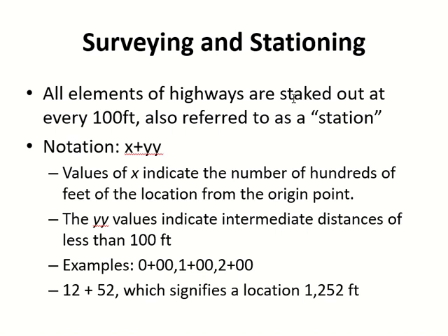Okay. So this means how much? 12 stations and 25 feet. Like total how much distance? 1200 feet plus 25 feet, so 1225. And if it was 1252.5, 2.5 will go where? After the plus sign. So before the plus sign, only hundreds. Then whatever is remaining is after the plus sign.